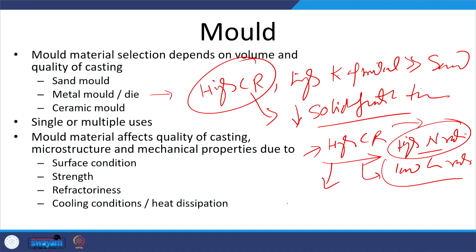That in turn results in a large number of nucleants during the solidification, and that offers the advantage of a fine grain structure.